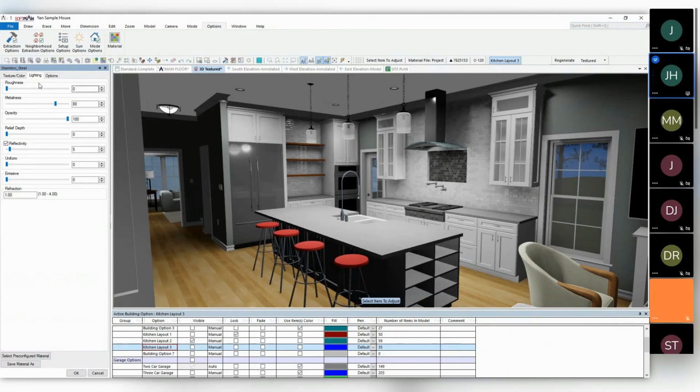You see the roughness, which can be used on things like brick and so on. It can also be used on walls and surfaces as well. If you've got a hot spot on your drawing, just by roughing that texture up a little bit, it's going to help dissipate the light for you on the model. So that's another option that you can use within the software.